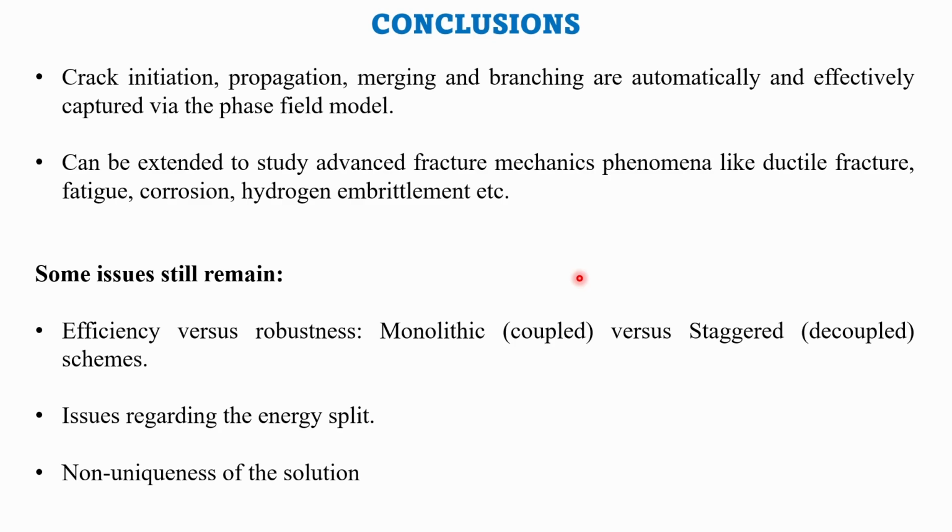We solve them together, we invert the entire stiffness matrix. Okay, we do not make them diagonal, we invert the entire stiffness matrix. It is computationally very, very expensive, but again, you will be able to make the unloading part of the stress strain response very, very vertical, which is effective for predicting the failure stress or the peak of the response.